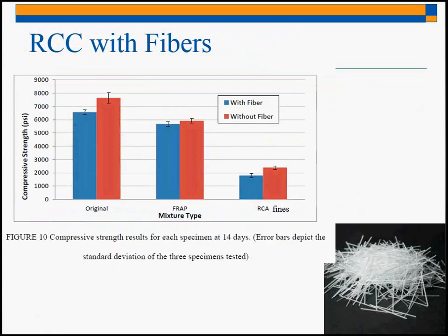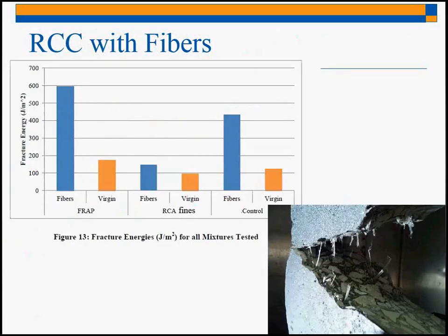So the work with fibers, they didn't show an increase in compressive strength. They actually showed a decrease. But again, compressive strength may not be the best test to be looking at when we're talking about pavement design. In terms of fracture energy, fibers can greatly increase the fracture energy of RCC, which is to be expected, as that is what has been seen with conventional PCC as well.